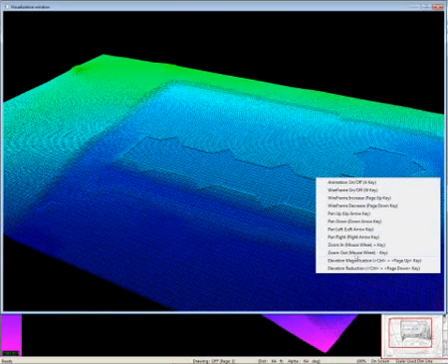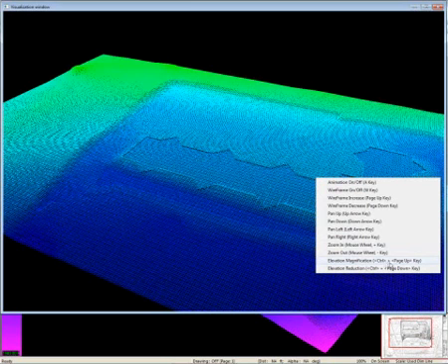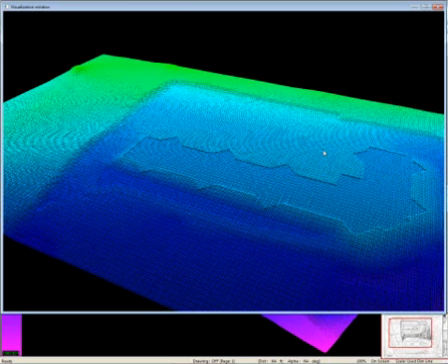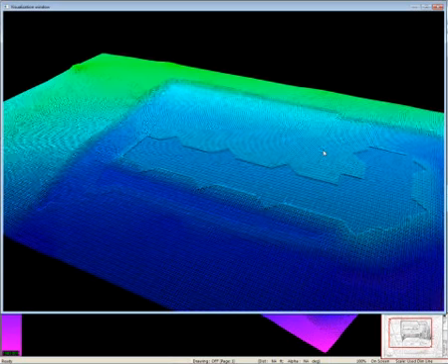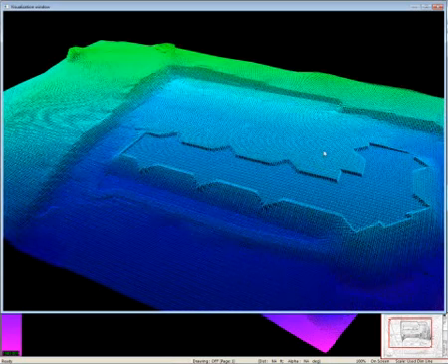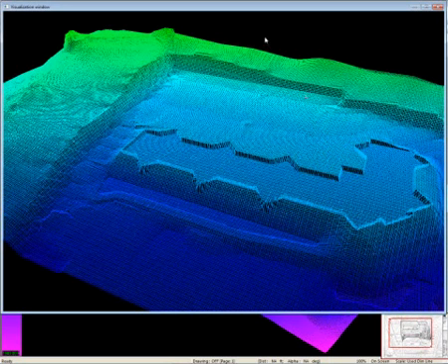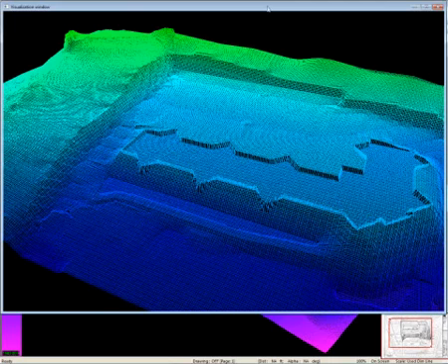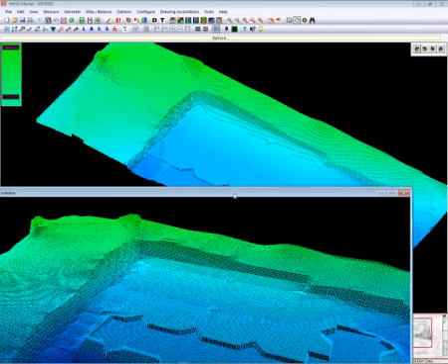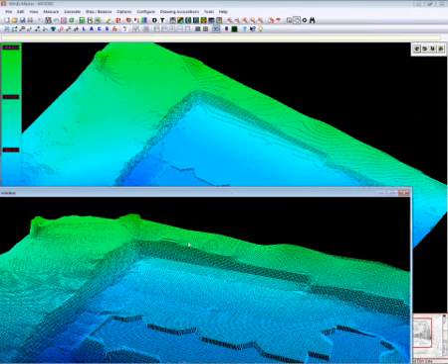You can also see all the other options you have, like I can turn up my elevation magnification by hitting the Control and Page Up key. I like to do that sometimes just to make sure that I don't have a spike somewhere that doesn't belong that maybe I couldn't see well. So you can see how that changes the model. And again, because we are already configured for dual monitors, you can put this on one screen, and you can have your actual 3D on the other screen, and compare the two and so forth. And again, go up and over and look all around on this.